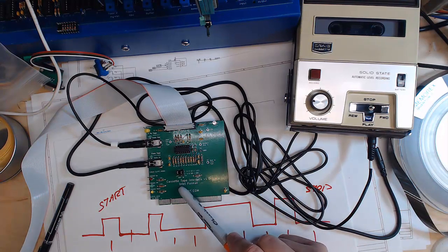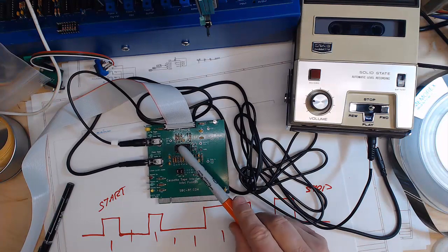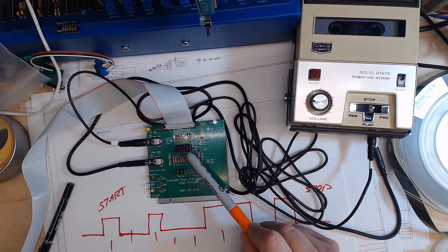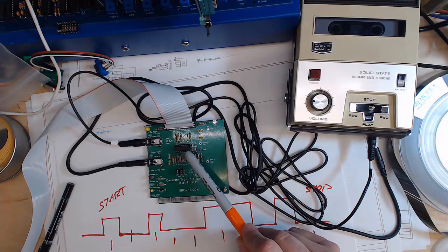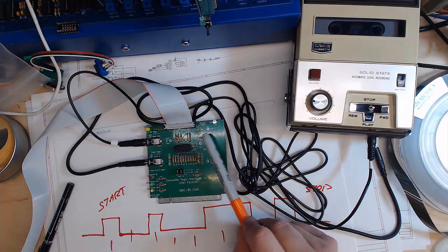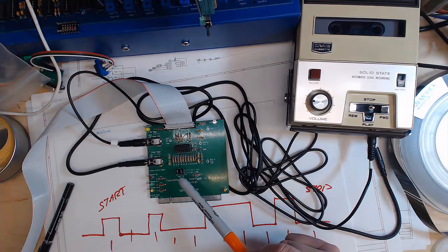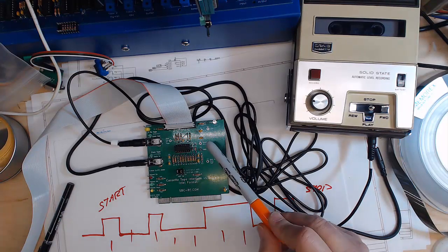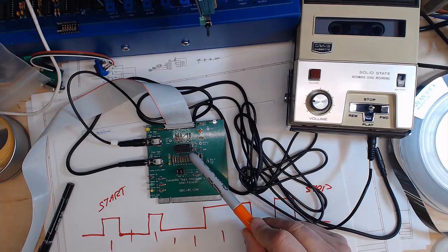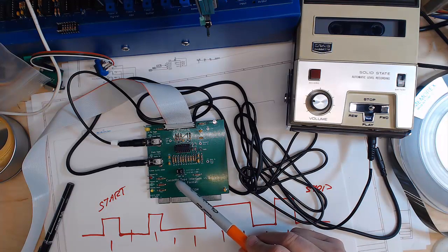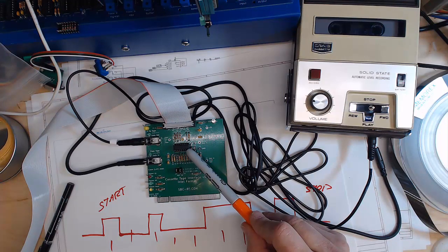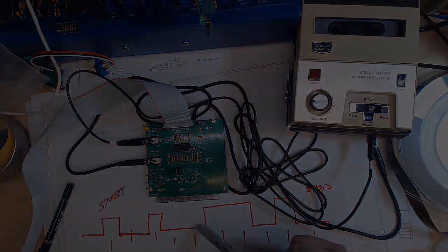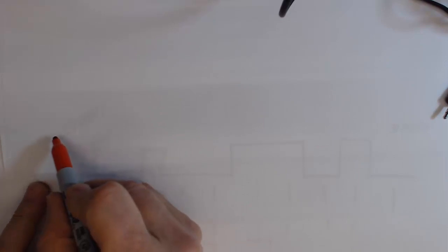So this is a board for the SBC-85. It's based on the Intel format. This is essentially right out of their data sheets from the MCS-80 series or MCS-85 series microprocessors. So this is all just Intel reproduced, basically. But what they decided to do was push all of the complexity onto the microprocessor and make the hardware as simple as possible. So this utilizes just a quad op amp, has one op amp for the output, and then 3 for the input. So let's look at how Intel decided to store this data.